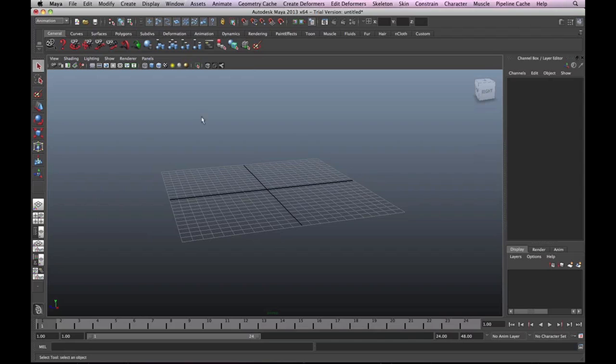You begin with a big empty 3D space and some very complicated user menus up here. With this pull-down screen in the corner, you have the ability to change the options you have in the menu in order to coordinate with what you're doing. For the sake of this tutorial, we're going to be dealing primarily with the Polygons menu. So go ahead and set it there now. As you can see, some of your options up here changed in order to coordinate with building polygons.